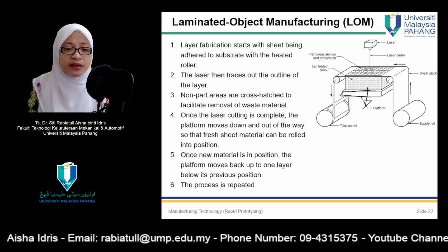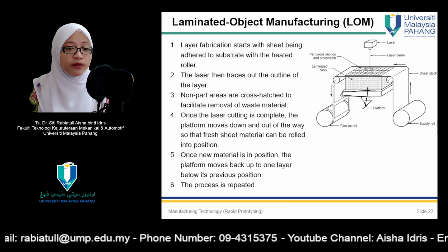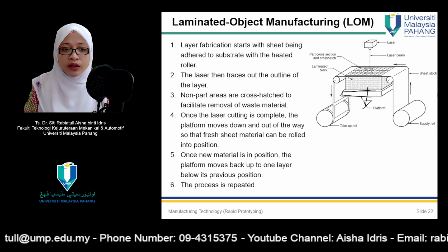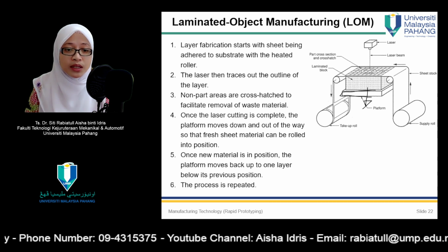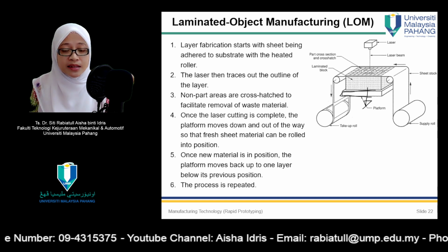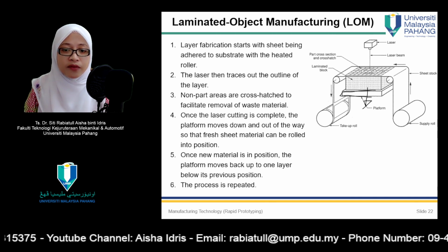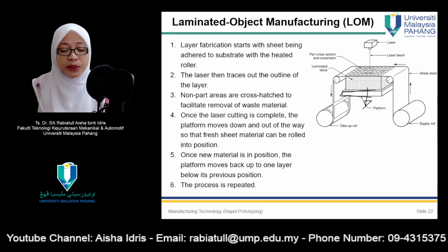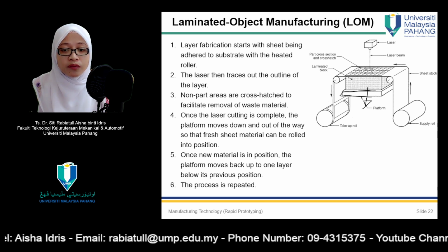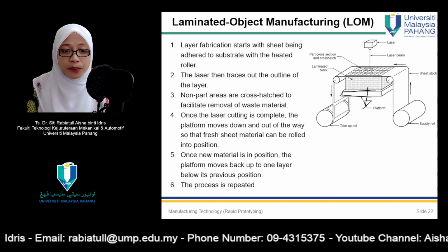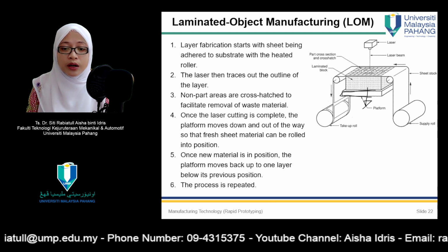The preparation phase in LOM consists of slicing the geometry model using the STL file for the given part. And the slicing function is accomplished by LOM Slice, the special software used in LOM. Slicing the STL model in LOM is performed after each layer has been physically completed and the vertical height of the part has been measured. This provides a feedback correction to account for the actual thickness of the sheet stock being used, a feature unavailable on most other RP systems.